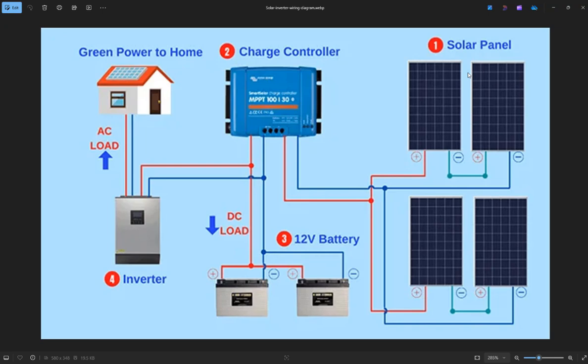That's the little box, the little adapter that the manufacturer sent to you when you got your laptop, right? So that's the adapter. What the adapter does is the transformer steps it down, then rectification, and regulation. That's how you can get a stable 20 volts.